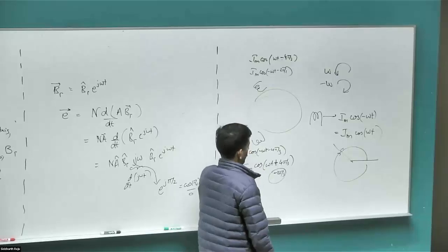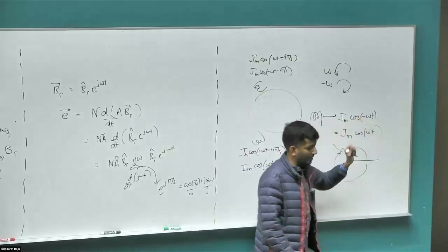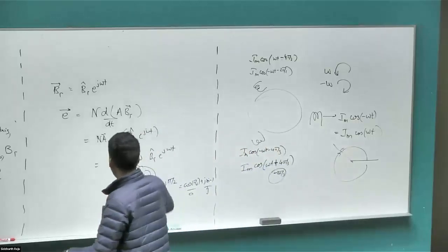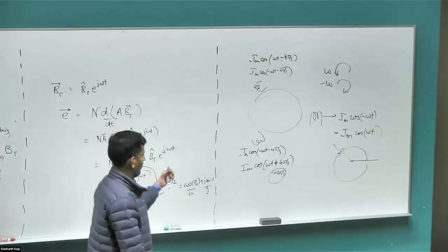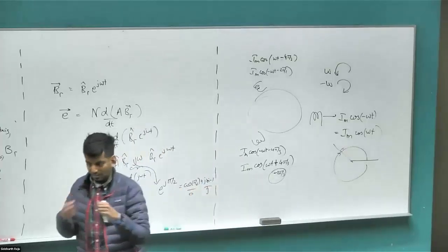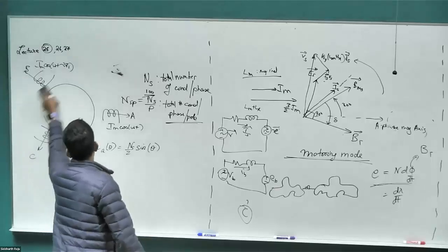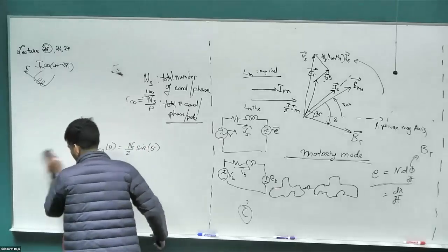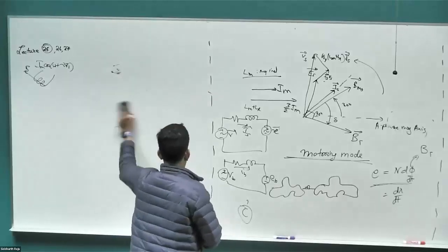So mathematically, when we see this expression of negative frequency, in reality, what that means is I've swapped the phases of the motor. That's how we represent the phase sequence, by putting a negative frequency there, in a pure mathematical sense. And this will come back when we go to the induction motor, where we'll see the rotor would sometimes have negative frequencies. Don't be alarmed, it's just that the phase sequence on the rotor has reversed. That means the direction is reversing in some sense. So this is all our permanent magnet synchronous motor is.